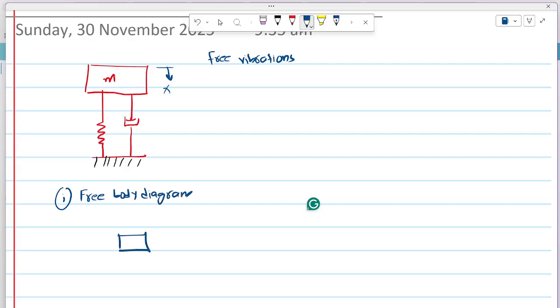So m would be equal to, if it is excited towards the bottom, there will be resistance from the spring force and from the damping force, or just call it Fs and Fd, and obviously it has some inertia as well. So you can write the equation of motion for this one, that will be